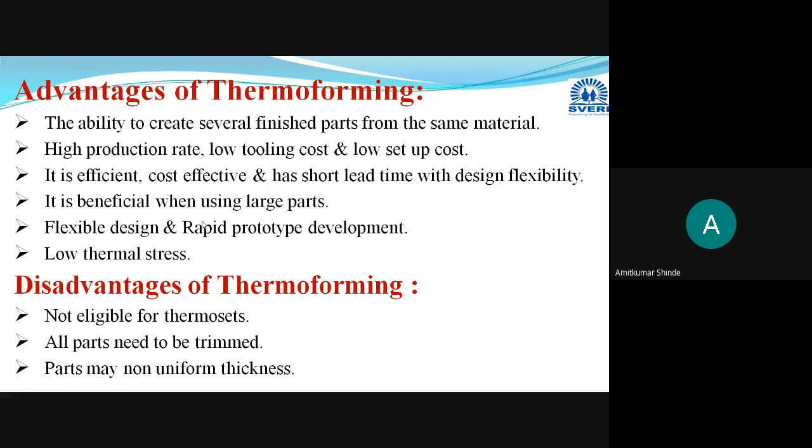Its lead time is short. Then there is design flexibility: small shaped parts and large shaped parts can be manufactured. And the thermal stresses are very low as we are performing preheating or heating before applying the force. These are the advantages of this thermoforming process.